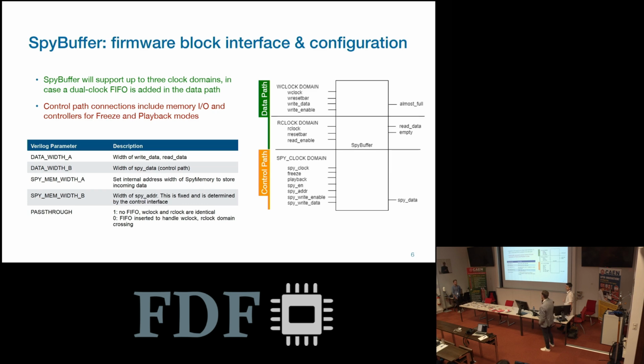Okay. Is this a generic of the Spybuffer module that you can configure? You mean the type of RAM? Normally you can do this configuration when you do the synthesis or implementation, if I remember right. No, it depends on what you say in the file. So maybe for this, in the instantiation of the Spybuffer, I don't know if there is a parameter where you can select the different type of RAM, and that is propagated down. But in general the memory is just described as registers.